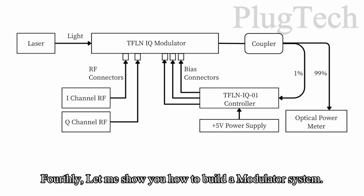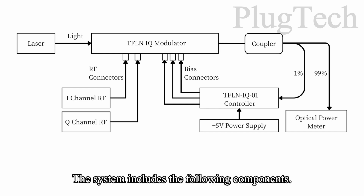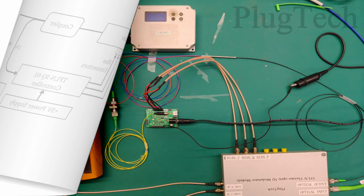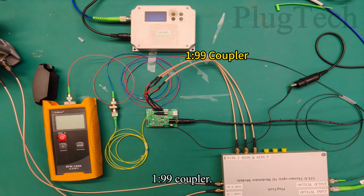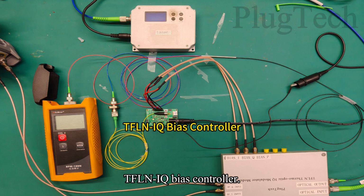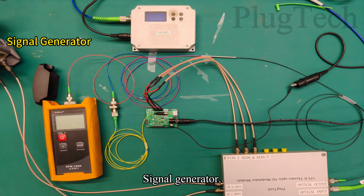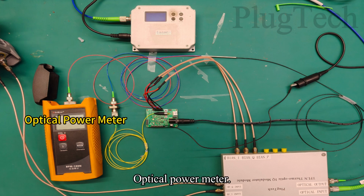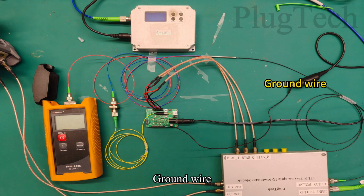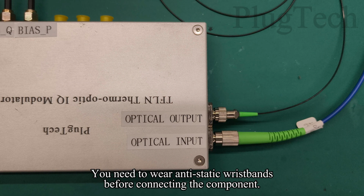Fourthly, let me show you how to build a modulator system. The system includes the following components: laser, IQ thermo-optical intensity modulator, 1 to 99 coupler, TFLN-IQ bias controller, signal generator, power adapter, optical power meter, ground wire. You need to wear anti-static wristbands before connecting the components.